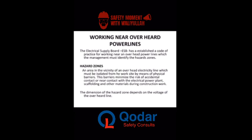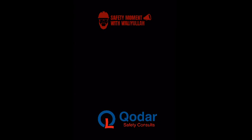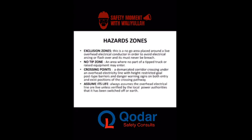Well, a hazard zone is an area in the vicinity of an overhead line that must be isolated before work is done. Let's assume we are working under an overhead power line. That place we are working has to be defined. It has to be isolated before work can be done there. We also want to remember that the dimension of the hazard zone depends on the voltage that is flowing over the overhead line. Now, in this hazard zone, there are different zones.